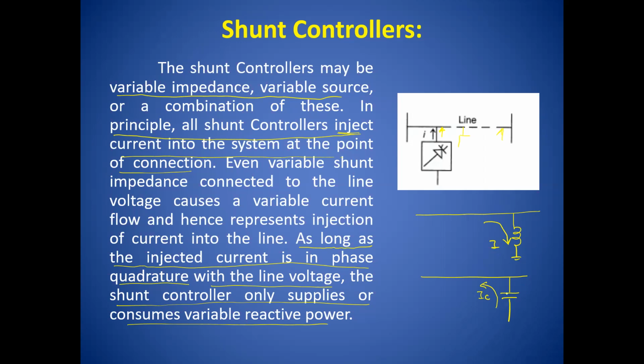So as long as this is a pure one, either it will consume or it will supply. In this case, it will consume the reactive power, and in this case, it will supply the capacitive or reactive power, isn't it? So our objective is to handle this current. If it is not in phase quadrature, definitely in addition to the reactive power, it also handles the active power.